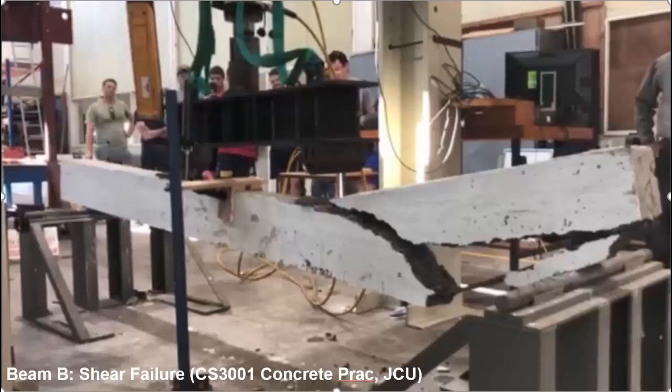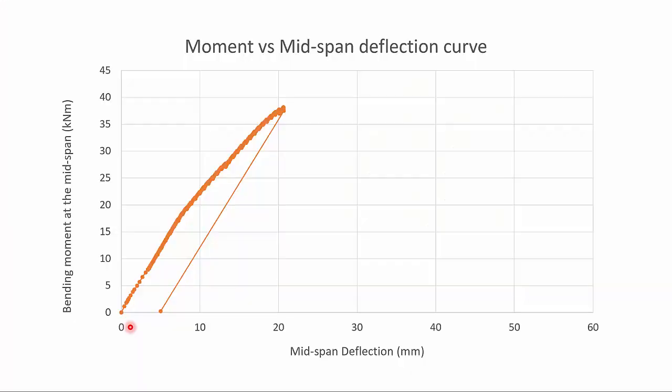As you can see, the shear failure is very brittle and abrupt, and there was not much deflection in the beam before it failed catastrophically. If you look at the midspan moment and midspan deflection plot for this beam, you can see it's a very brittle failure. As soon as the beam reaches its maximum moment capacity, around 38 kN-m, the beam abruptly fails. There is no yielding of the beam, no yielding of the steel reinforcement. And the midspan deflection is very small, just around 20 millimeters.